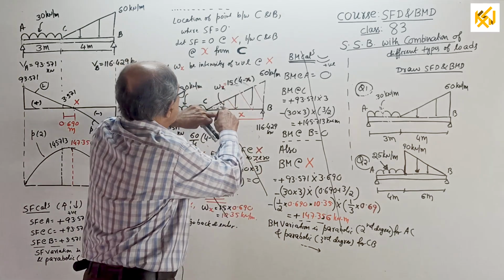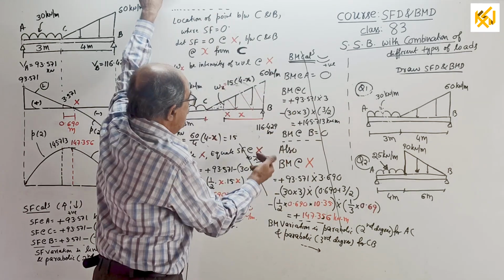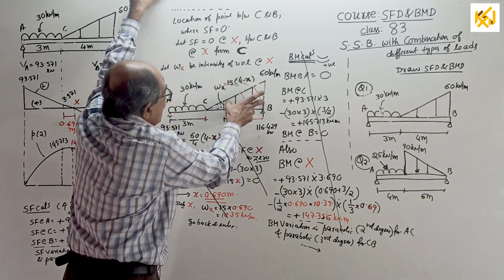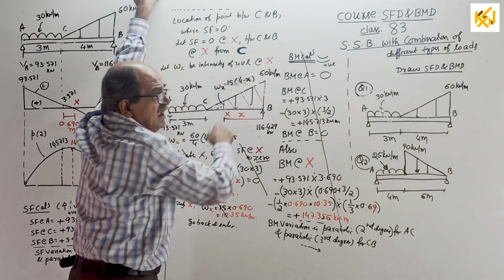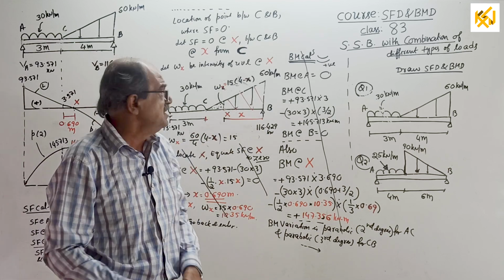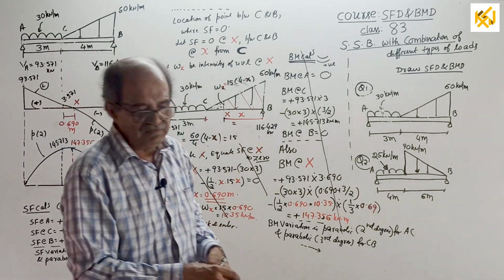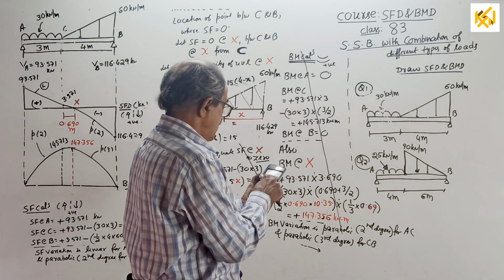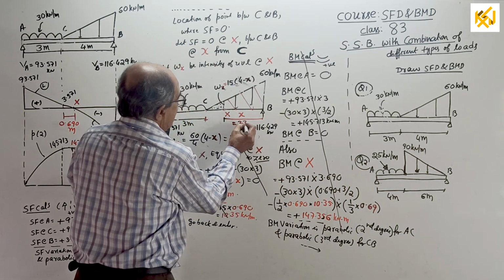See. Now, shear force 0 here. Look that side. Right side you are seeing, right up is negative, minus 116.429 plus total load here, 15 into 4 minus X plus 60 divided by 2 into X, which is the total load, equated to 0. 100% your X will come. See, this is called confidence. I am not calculating. I already got 0.69 from here. 0.69 minus 4, 3.31 meter. Guaranteed it will come.